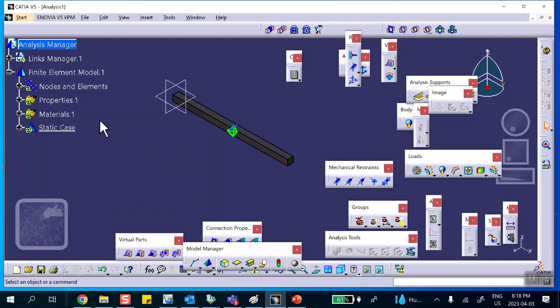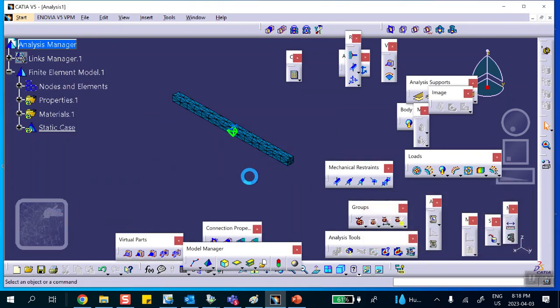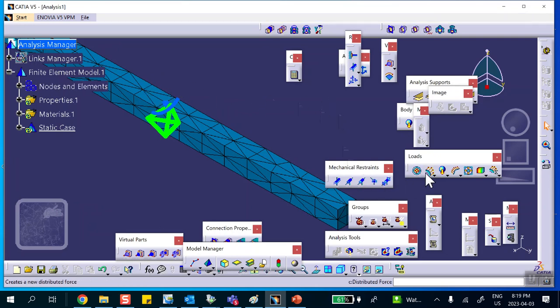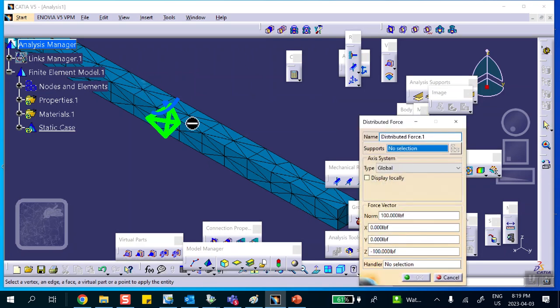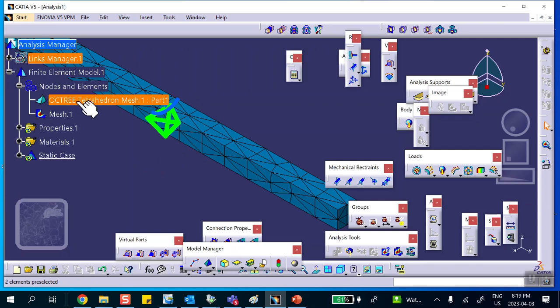You'll see why in a second. So you can see the mesh. However, I want to apply my transient load at a particular location here, which I cannot just take like this. Notice that in Catia you cannot apply load directly to nodes. So I need to make sure there is a point that I create where I want to apply the load, and that point becomes part of the node system of the problem, which means that you cannot do it in generative structure analysis with this type of mesh.